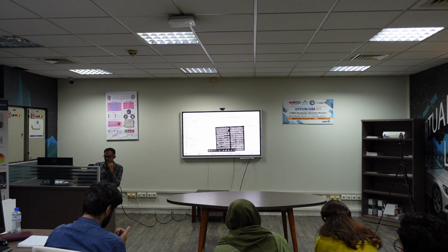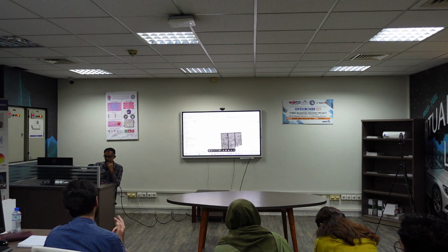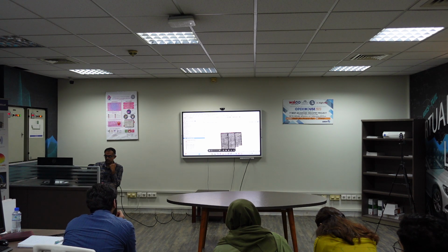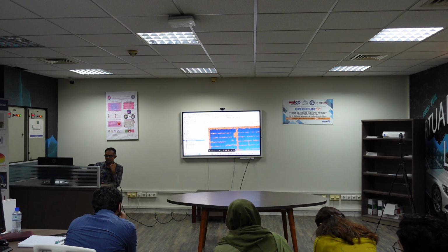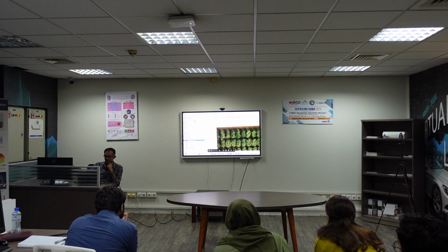It depends on the way you interpolate. Your interpolation is highly dependent on the points you have sampled. So you have to ensure that the points it is sampling are the ground points. For example, now you can see that although the crop plot is this, there is a significant gap between these two.